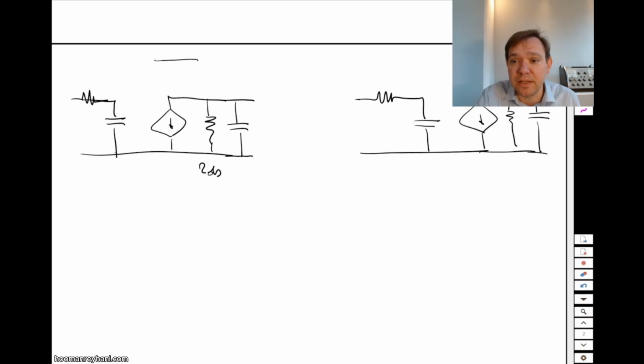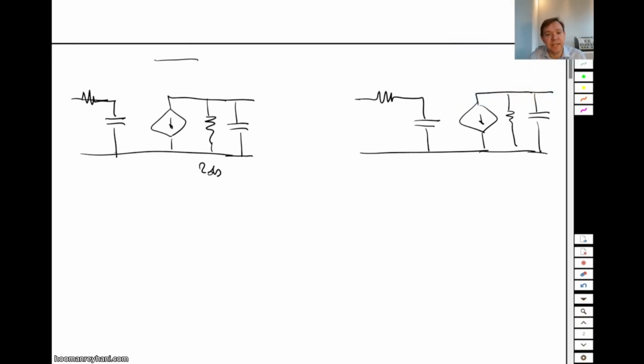So we have two gm's, and this is the gate resistance of the gate electrode. This is CGS, this is CDS. Just for my convenience, I'm skipping the gate drain capacitance, or I'm assuming I've unilateralized the device, also something that we're going to talk about in the course.